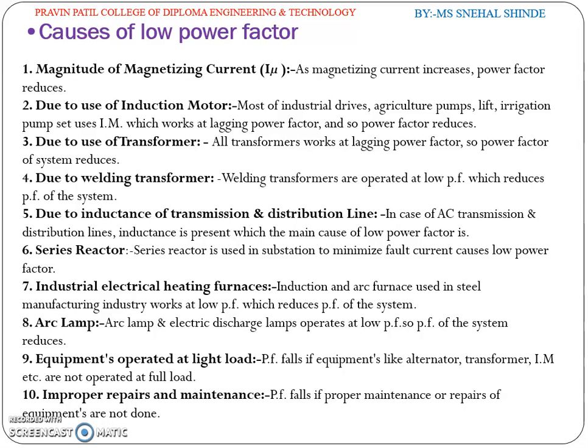For example, the induction motor has a reasonably high power factor of 0.85 at full load, 0.8 at 75% of full load, 0.7 at half load, 0.5 at 25% of full load, and as low as 0.1 on no load.